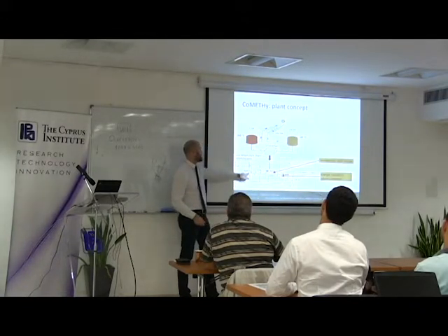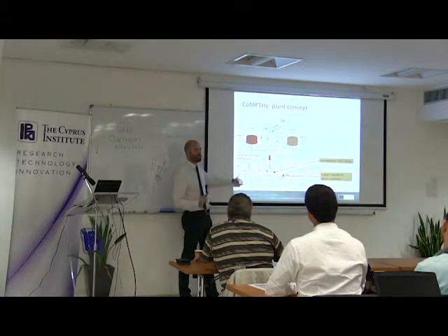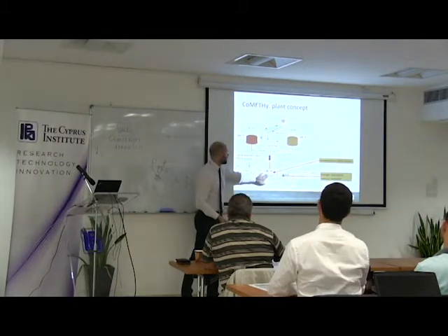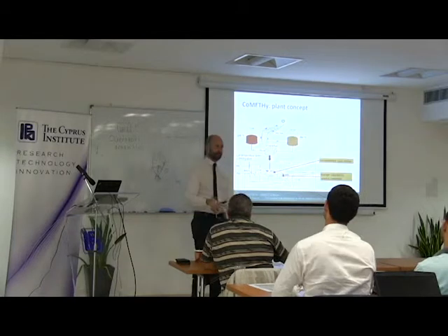This is what's inside the chemical plant. The chemical plant must preheat and boil the water in the steam generator, must preheat the mixture of methane and water fed to the reactor, and then must provide the heat required by the reaction within the reactor.